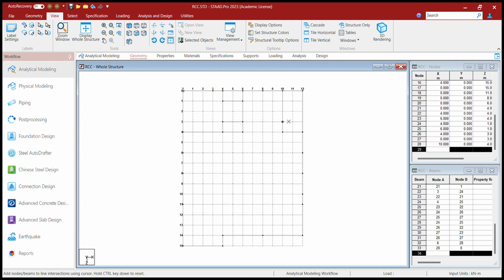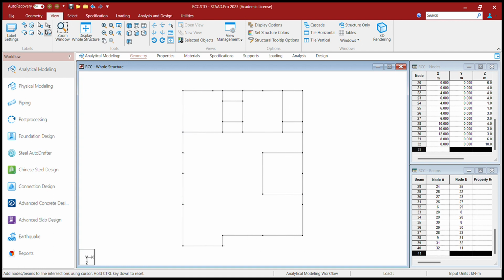At this, we complete 2 and 1, so 3 and 1. Then next here this position, and then here we need to create one member here. Let us create one beam here and then afterwards we will create. So this distance it is 4 meter, 4 meter, 4 meter, 4 meter. There is an additional point here. I wondered where this 2 meter point came from. It was directly here earlier. It is additional. We'll delete this point.